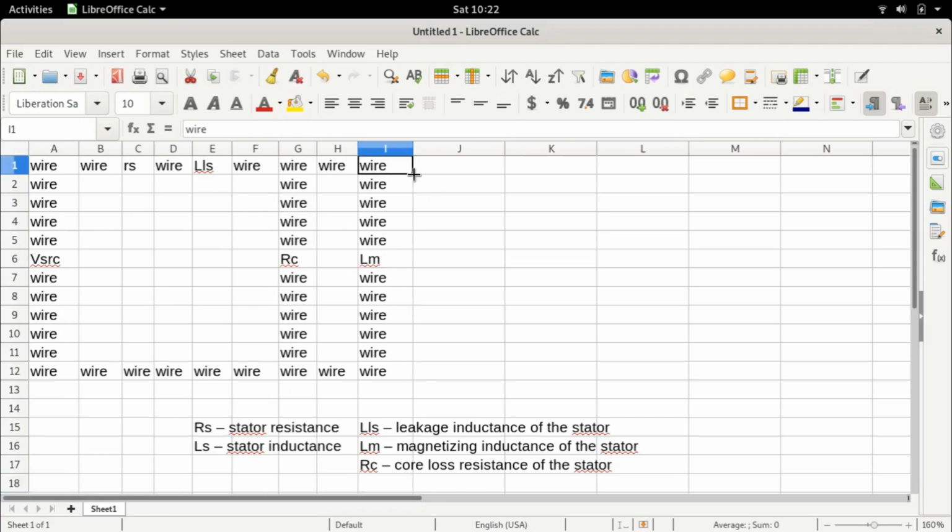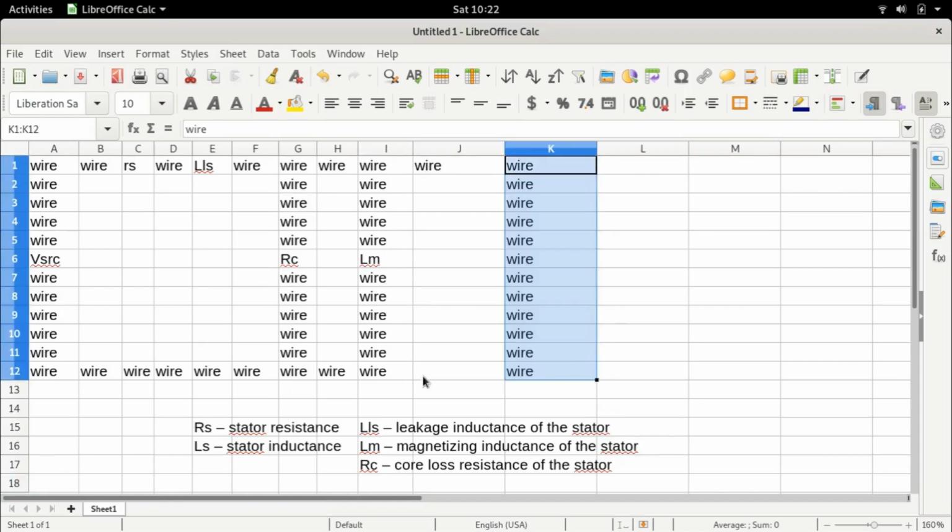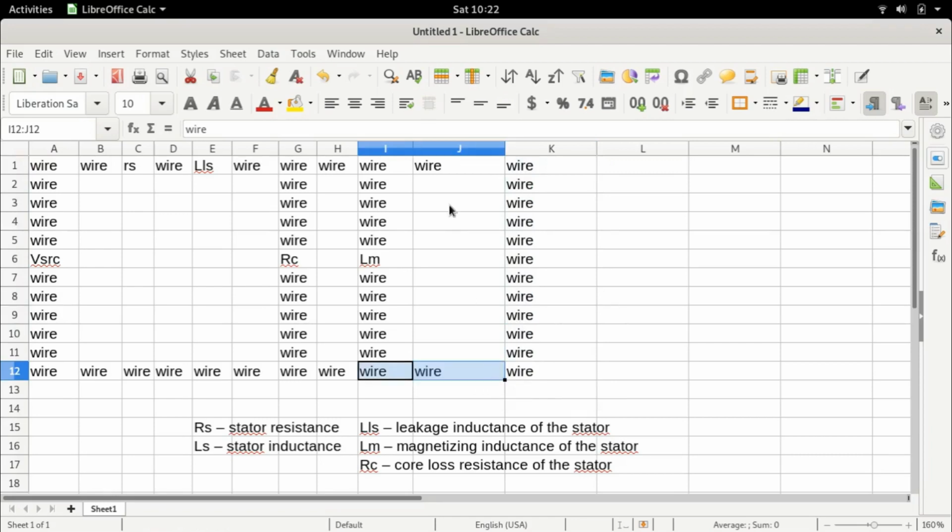So let's keep going, because what happens is we are talking about an induced EMF, right? I'm just going to stretch it a little and produce this. When this current flows through, and I'm going to remove the short circuit because it's kind of misleading. So let's just remove the short circuit. When we apply a single phase voltage, this single phase voltage flows through the circuit, right? There is a resistive drop, there is a leakage drop, and the rest of it flows across the magnetizing inductance. The current that flows through the magnetizing inductance results in a magnetic field.